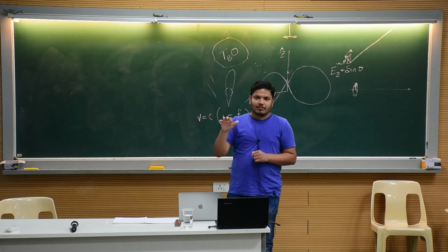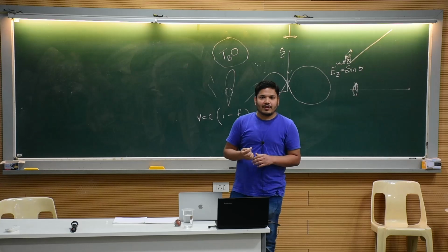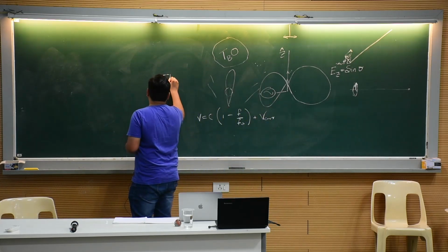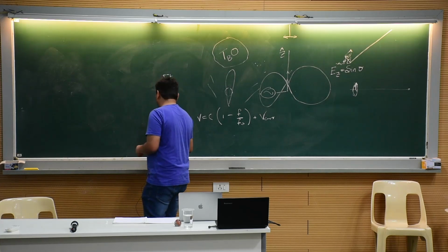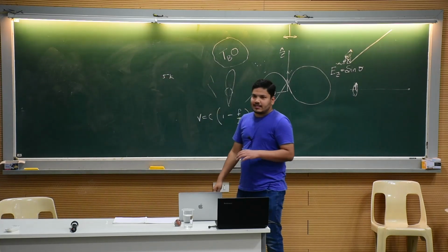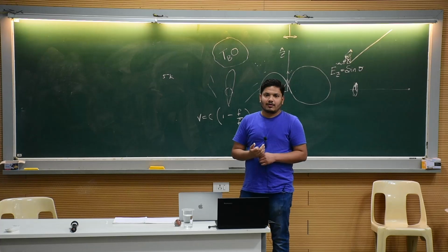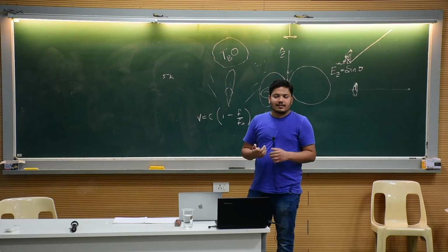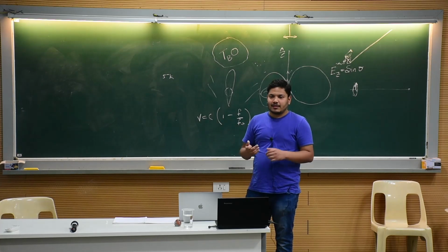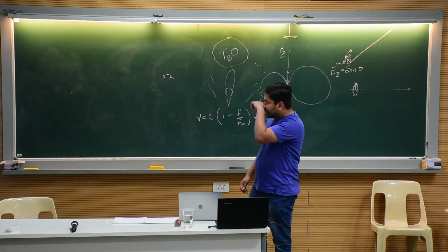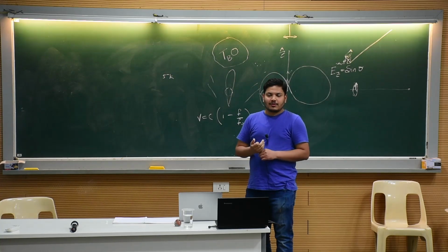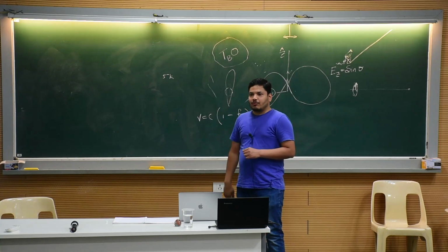We assume this background temperature is 5 Kelvin, which is basically the CMB plus your atmospheric contribution. The CMB is at 3 Kelvin and the atmosphere also adds a little bit of temperature. So we can assume your antenna is pointing to some 5 Kelvin source. Then you point it to a nearby wall.